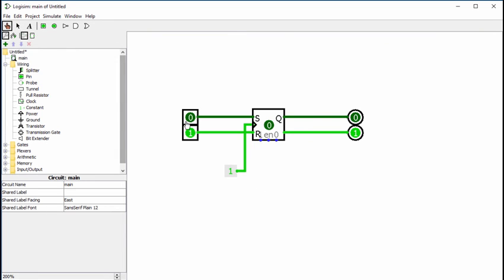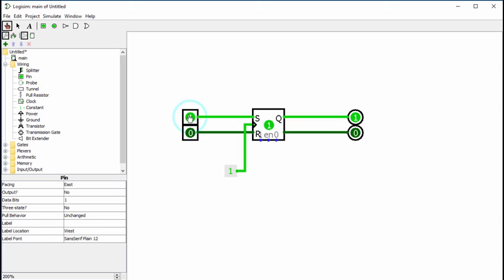Now this will work. So if I go to a set, it sets, remembers, resets, and remembers. The difficulty is when I go to 1, 1. It doesn't display the crazy behavior of our NOR gate. It's been fixed. And to discover how it's fixed, we can see that it's taking on a value and remembering it. So it's acting like a memory state, a remembering state.